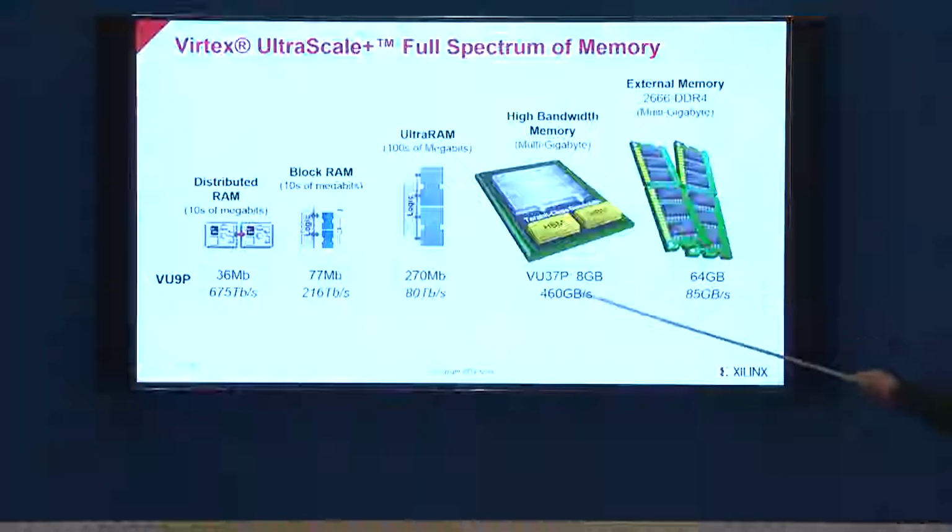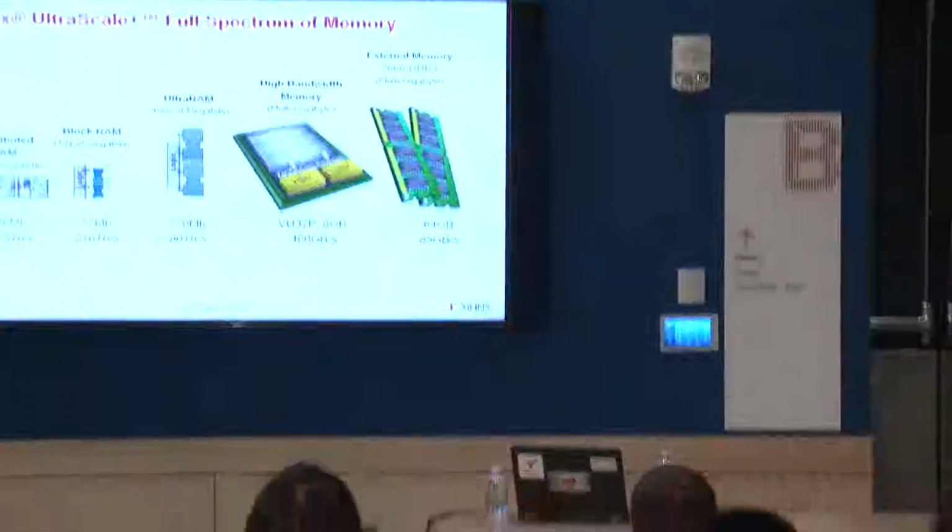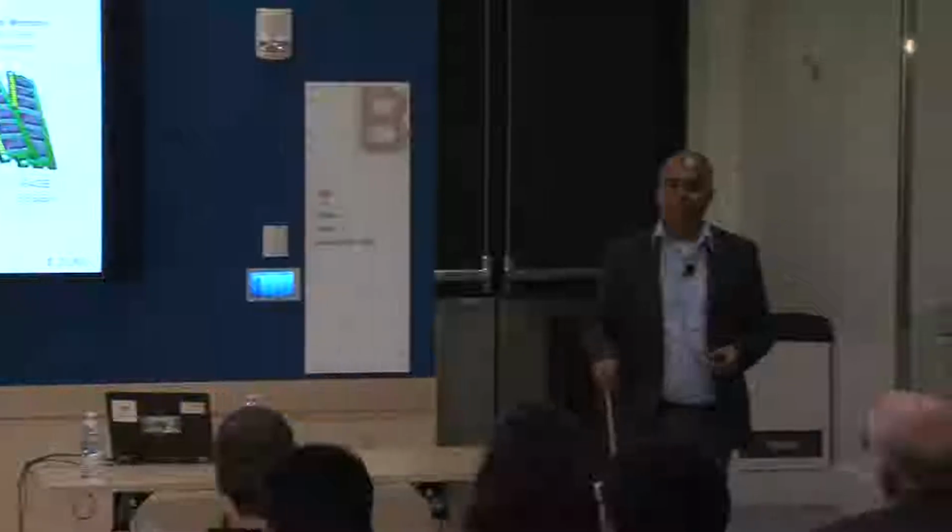Most of our devices do not have HBM. There is only one device which has HBM, and it will be released next year. But on most devices, you can build multiple DDR memories based on what you are doing, right? So when we say programmable, flexible, these are the things I wanted to share with you, because these are the building blocks with which you will build a deep learning inference engine.